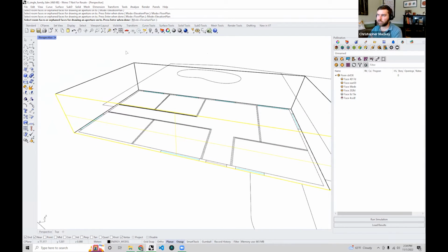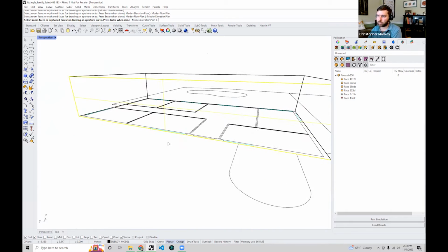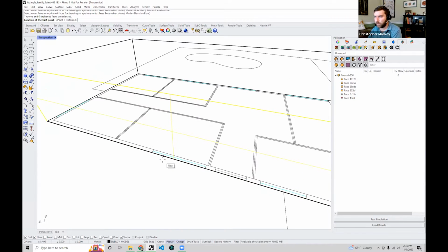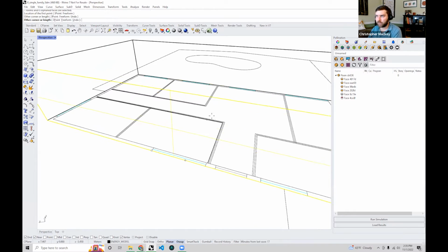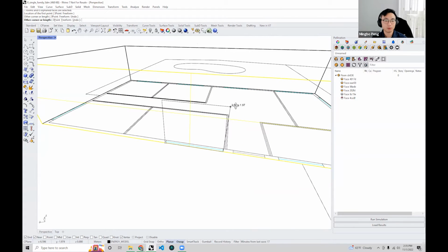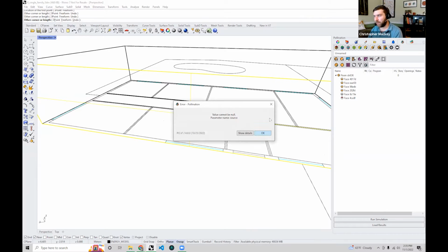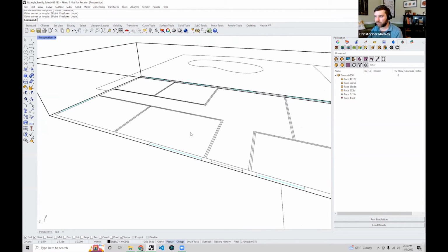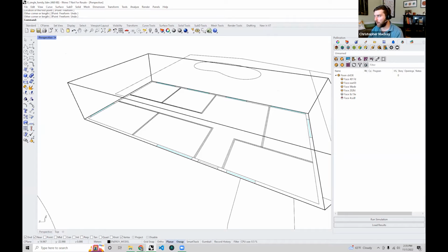As long as that mode is floor plan, once you have that wall selected, we can simply draw, using our snaps here, along the wall surface. Oh, I actually had elevation plan selected. So probably what I should do is exit out of this. I'll just hit escape for a second and redo this draw apertures command.